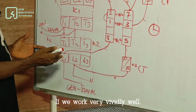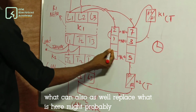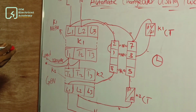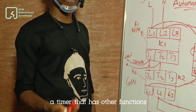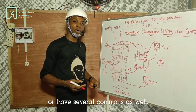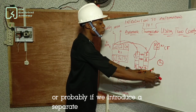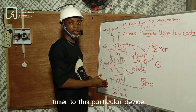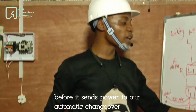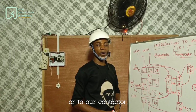If we watch very vividly, we will understand that what we added here can also be replaced by a timer that has other functions, that can switch in between two sources of power, or that has several commons as well. So if we introduce a separate timer to this particular device, what you will notice is that the device will have to delay before it sends power to our automatic changeover or to our contactor.